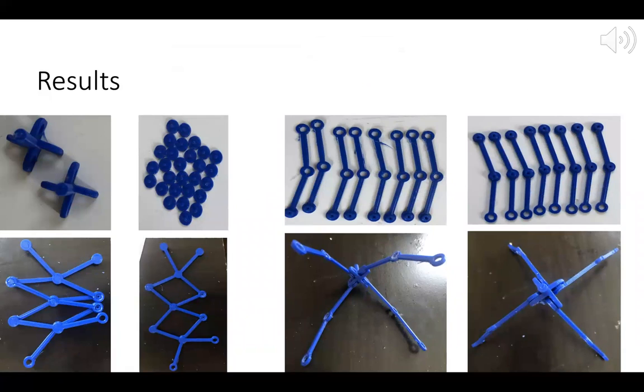Here are the final results of my 3D printed parts on the top. I did not end up needing the caps, which are the second picture on the top row. And the bottom row is the pictures of the final assembly for the 2D hinge and then the 3D hinge. I will say for the assembly of them, I had to take an X-Acto knife and trim the original parts to make them fit together better, because the 3D printing left extra thickness that I wasn't anticipating.